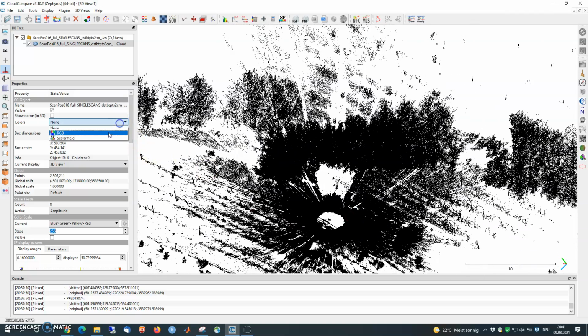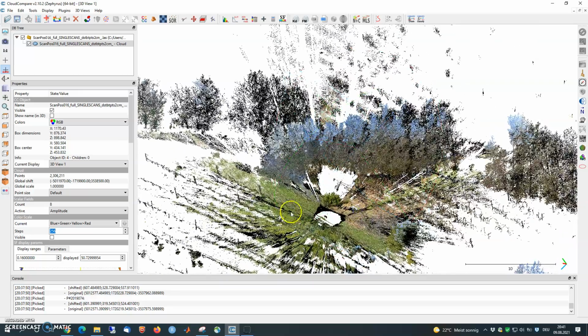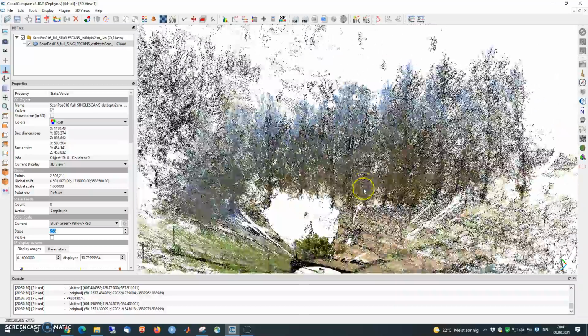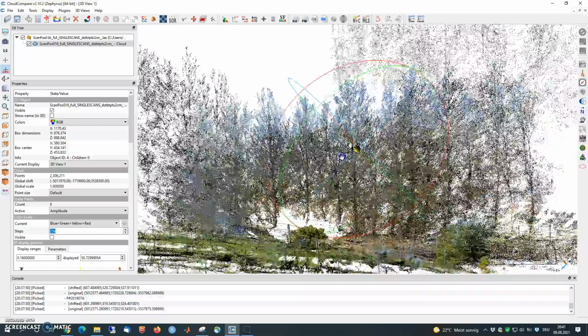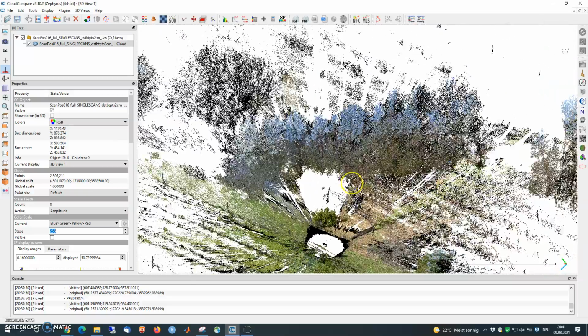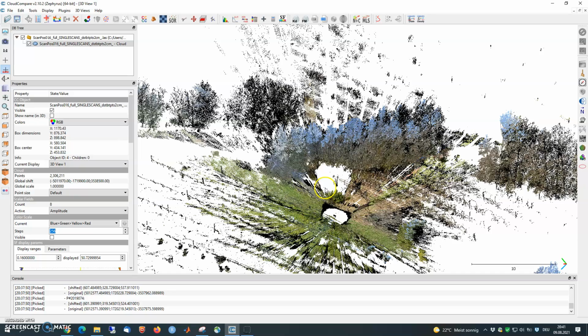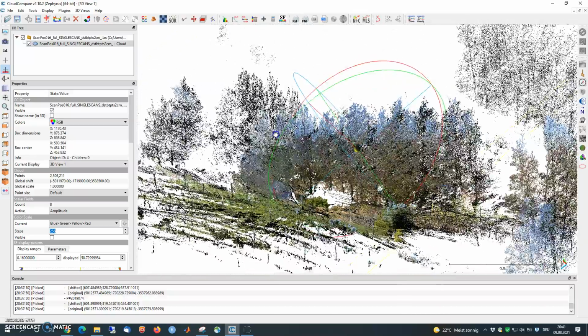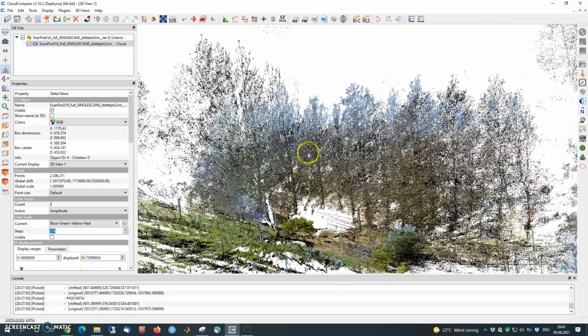In this case, the RGB information was generated with a camera on the top of the scanner. And you see, for example, that the upper parts of the trees get bluish points. This is because the photos will take part of the sky, and then the tree tops are very likely to get some bluish or whitish colors.